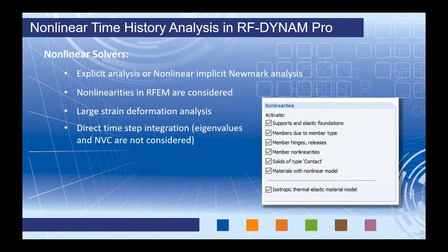So now moving on to nonlinear time history analysis. Again, this is something new that we just recently added. And now we have the ability to define two different solvers to utilize, either the explicit analysis or nonlinear implicit Newmark analysis.